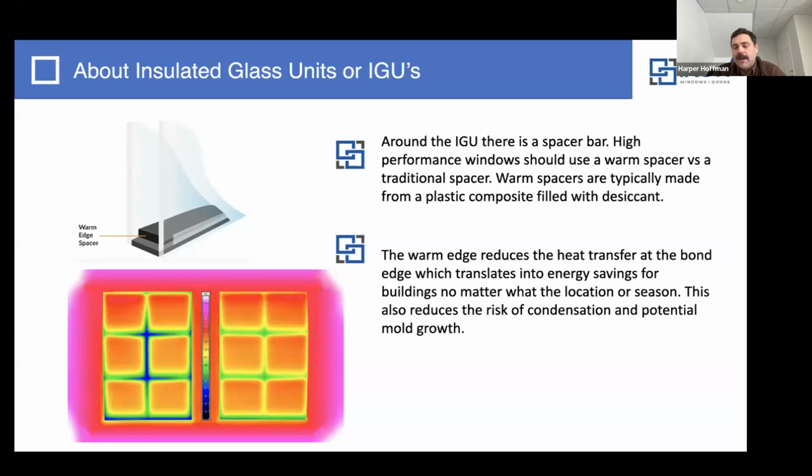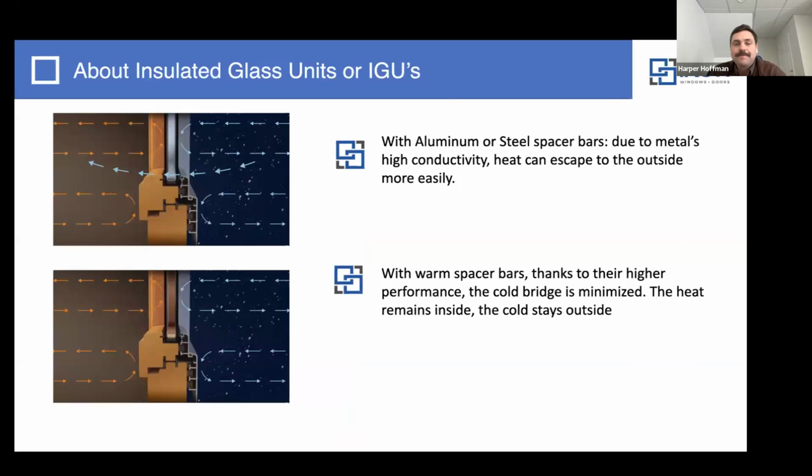So it's a big hygienic component, because if any kind of vapor or moisture is sitting there, it can cause mold, it can cause mildew, it can cause all kinds of things. It can corrode your material, if it's metal sitting there, or it could cause rot in wood. So this is such an inexpensive component of the assembly that really has a big effect on helping it out.